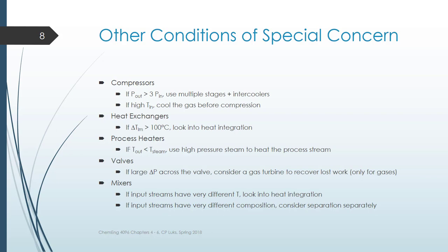Valves, we're going to be careful about the pressure drop that we have across that valve. If you have a very large pressure drop and you have a gas, you might want to consider putting in a gas turbine to recover some of that lost work.